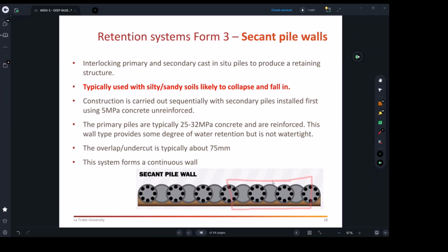Right, so talking about constructing this section, you're gonna be excavating for the non-reinforced section first, and pour the non-reinforced piles as they are, like a full circle, without reinforcement. Then after they are 30% hard, they are still excavatable. You're going to excavate for the reinforced piles in between, as shown, and you place the reinforcement as discussed, and that's it. So this section is done.